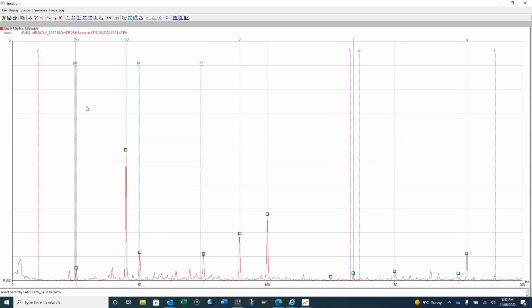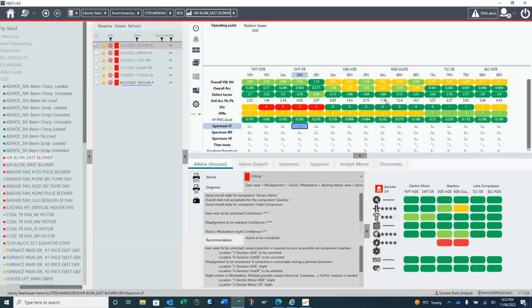You go with the gearbox. Yeah, gearbox. Vibration of the motor is very low. Is that an anti-friction bearing or a sleeve bearing? I don't know, sir. You mean the motor bearings? I think anti-friction, not sleeve. Okay, so you go with the gearbox. You don't want vertical and axial? No, the vibration is low. No problem with the motor. Okay, horizontal for the gearbox.